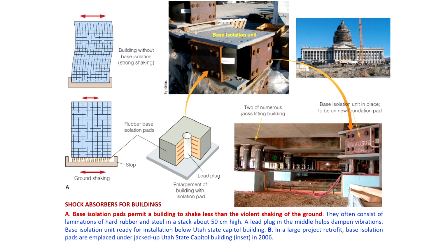Base isolation absorbs the ground shaking and lateral movement which can damage the building. These are rubber base isolation pads, made up of lead plugs in between, with the rubber on the side. This takes up the complete ground motion, so the building will just sway, it will not move like what we have here.